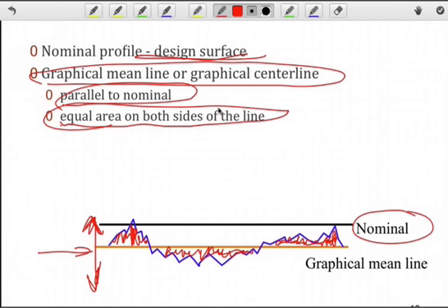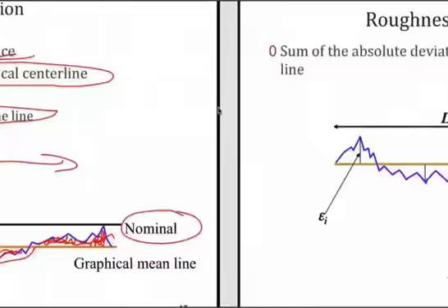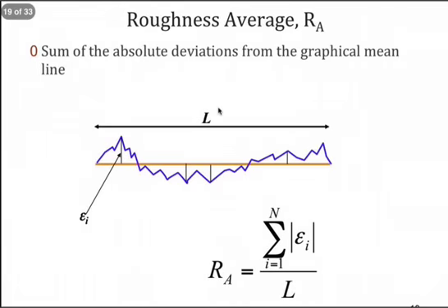Now, when you did this in 248, you measured surface roughness. You took a scribe, which rode along the surface, and you dragged it across the surface, and you produced this blue irregular curve here, which represented one set of data in a line going across the surface, and then you could repeat that multiple times. Well, how do we come up with a metric that would tell us something about that roughness?